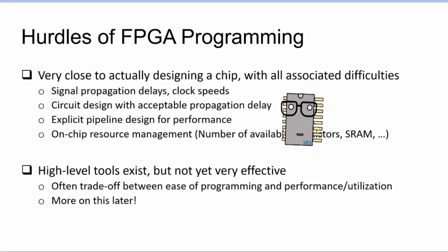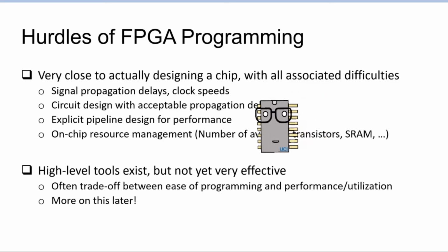There's also trying to do circuit design, which results in acceptable propagation delay, because otherwise you'll get a slower clock. You also have to do explicit pipeline designing for performance. It kind of turns into doing computer architecture design, designing your own processor, things like that.